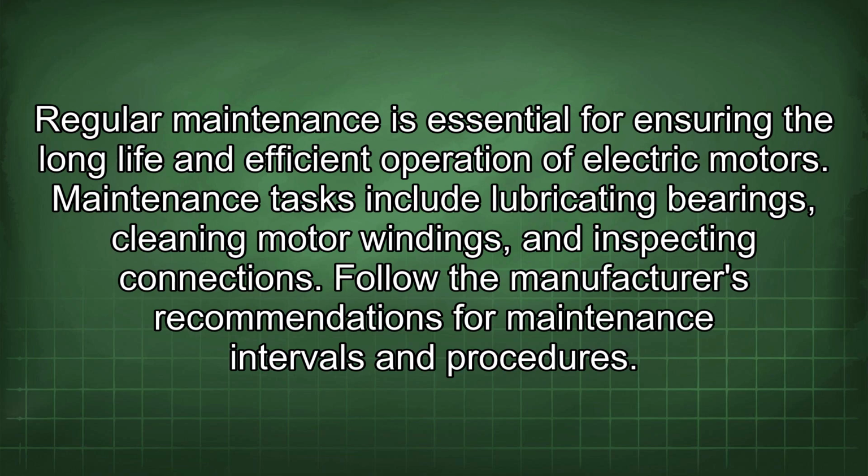Maintenance tasks include lubricating bearings, cleaning motor windings, and inspecting connections. Follow the manufacturer's recommendations for maintenance intervals and procedures.